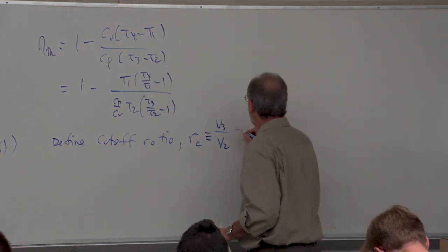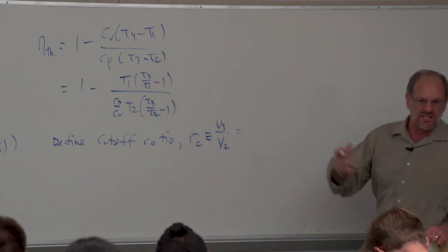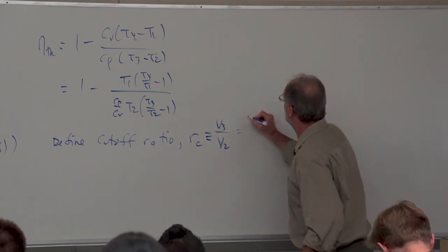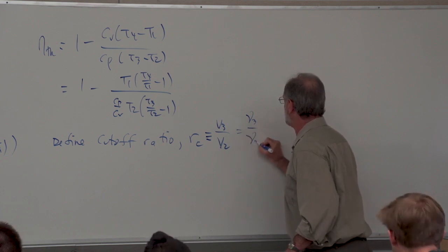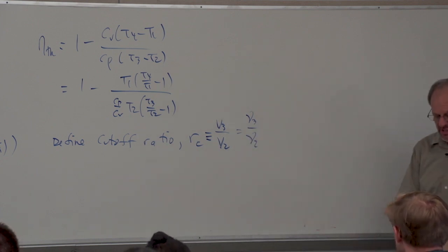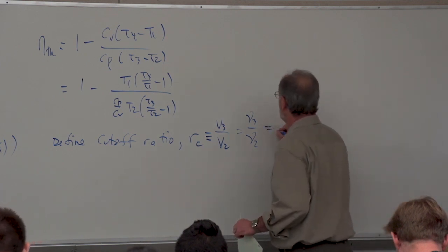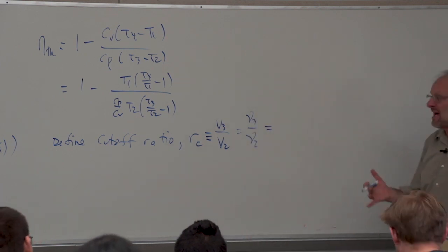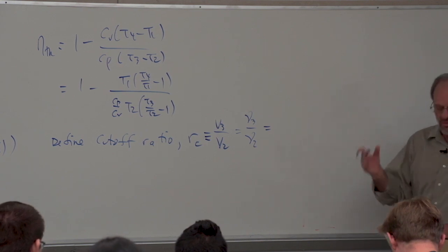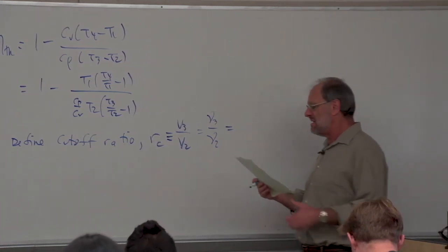Now, let's keep in mind that we're dealing with a closed system, a system of constant mass. So if I divide numerator and denominator by mass, I just simply end up with the specific volumes. And then also, I would remember that we do have ideal gases, right? So PV is going to equal RT.